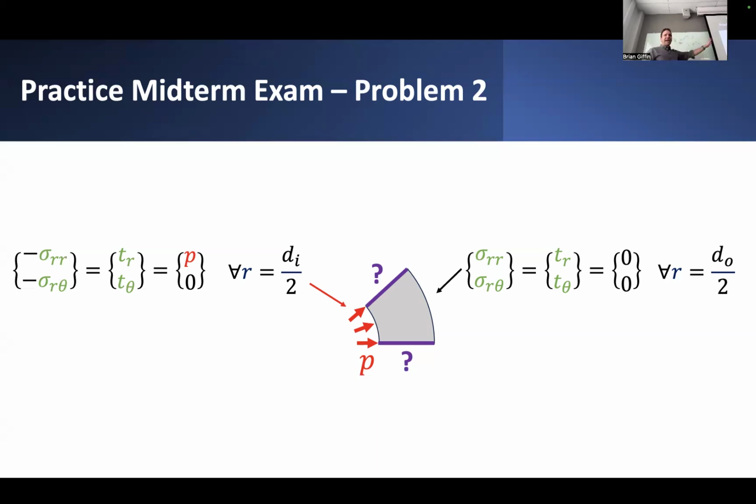All right, but how does that manifest in terms of the boundary conditions? That's certainly something consistent with what you said. There are displacement boundary conditions. Indeed, if we have this symmetry plane, then we're saying normal displacement along that interface has to be equal to 0. But what about the tangential displacement, or the displacement now in the radial direction? Is that constrained?